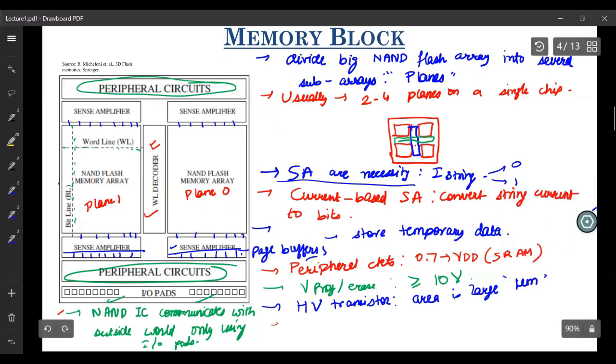So first, you will need a charge pump, right? Because you need to apply such high voltages, and the voltage available to you from the cell in your mobile phone or such IoT mobile devices is about 5 volts. So you want to convert that 5 volts to 10 volts or even higher. 3D NAND flash ICs, for instance, require up to 20 volts for programming.